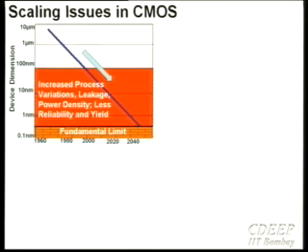It turns out that the power density increases, and if you look at some of the chips of today, you're close to about 100 watts per centimeter squared. That's not a real limit, but with today's technology, without any fancy cooling methodologies, it's certainly very difficult to go above 100 watts per centimeter squared. Based on all these, power density and increased variation, one has to also look at reliability.